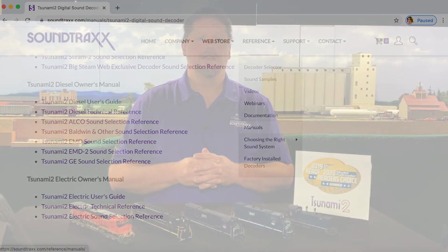Now, part of the reason this had to be done is because a diesel prime mover sound takes up so much more space than an exhaust chuff, because with an exhaust chuff, you have basically 4 chuffs. But in a diesel locomotive, you have the startup sequence, the idle loop, the notch idle to notch 1, notch 1 to 2, 2 to 3, 3 to 4, and so on, and all those individual. So it takes up much more memory space, and especially since at SoundTraxx we don't clip or edit the sound files any more than just cutting them on end. That way you get the full sound spectrum, so if you have speakers that are capable of reproducing those low frequencies, you can hear those tones, and we'll get to that here in just a second.